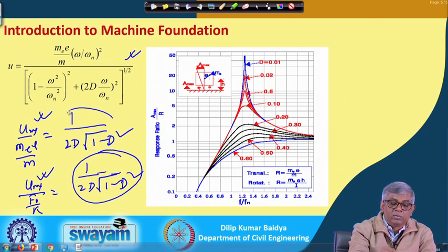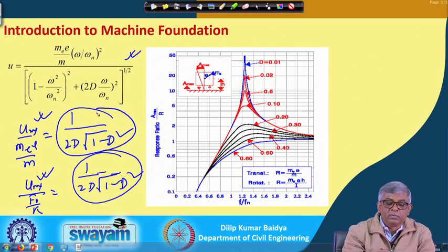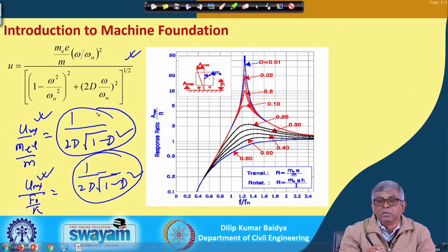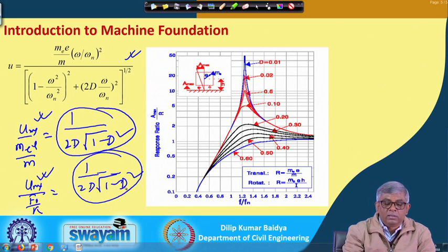So, you can see both for the rotating mass system and the constant force system, the resonance amplitude depends only on the damping value. The procedure for how we have done this I am not going into, but what frequency ratio this is becoming, I will show in the next slide, for both of these.